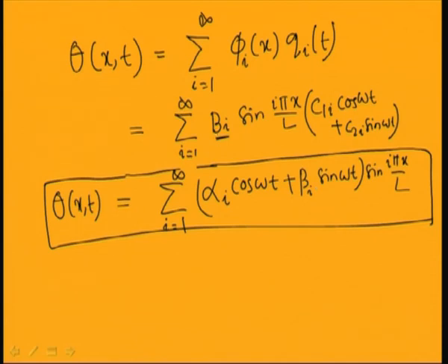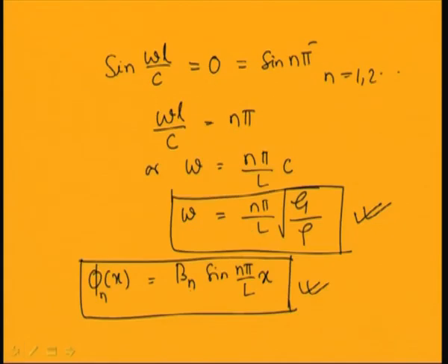So, you just observe that for a different mode, this b i will be different. So, for n modes you will have n number of constants b1, b2, bn. Like in case of multi degree of freedom systems, here you can normalize this and find the normalized value. To find this normalized value you can apply the orthogonality principle. The orthogonality principle can be applied in this way.